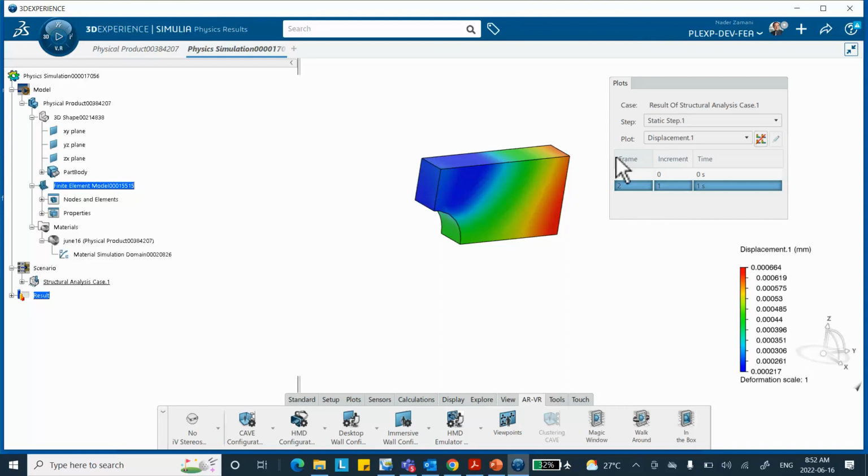Better go and review this stuff for tomorrow. You put 4,000 pounds on that face. Once you take 1/8 of the part, that 4,000 pounds is on how many planes being applied? 1/8, you're right. But that 4,000 pounds at the end, on how many planes was it being applied before we took the symmetry? If you count the number of things that's being applied, there are four of them. So don't go by the fact that I took 1/8 of the model, I should take 1/8 of the load.